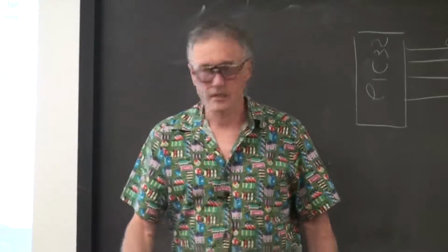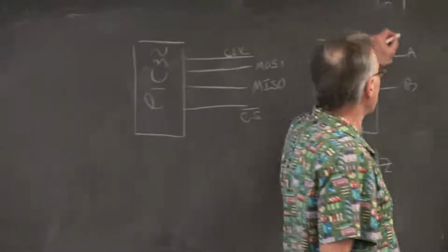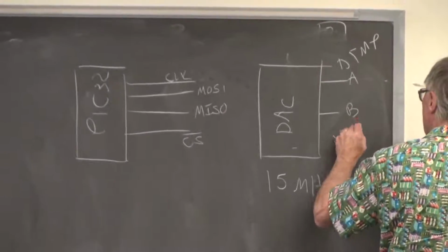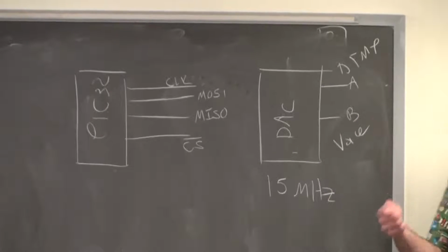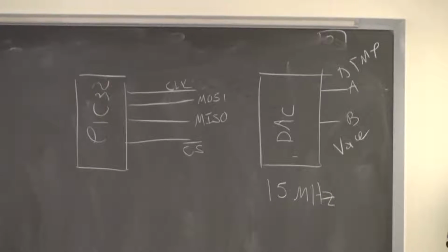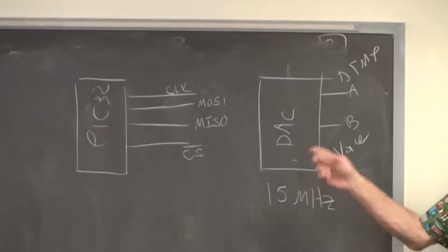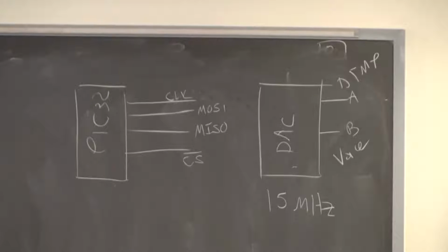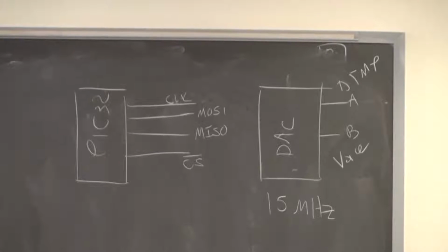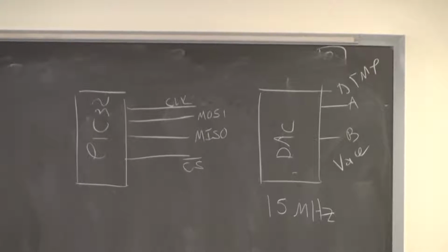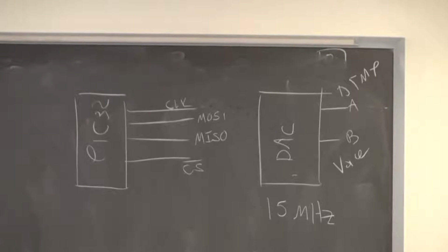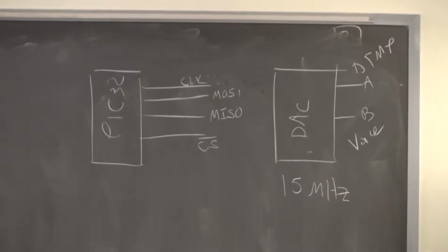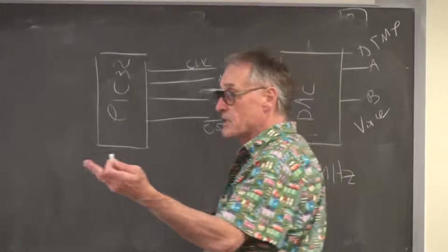I would suggest using one channel for the DTMF and the other channel for the voice. We have stereo speakers, they're going to map in an obvious fashion to these outputs. You plug the stereo speaker into it, you'll get voice in one channel, DTMF in the other. You can debug by moving them to and from your ears. There's other ways to do it.